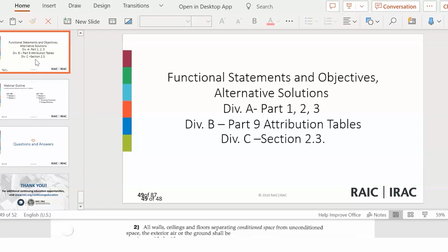We went over this a little bit when we looked at Part 3. You've got to look for what your occupancies are. Always look at what your occupancies are. What are the wishes of your client? Maybe your client does not want a wood frame building. Maybe he wants a steel frame, non-combustible frame building. So establish the requirements of your client, right? That's what he wants.